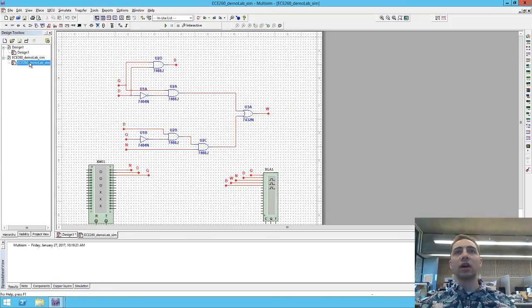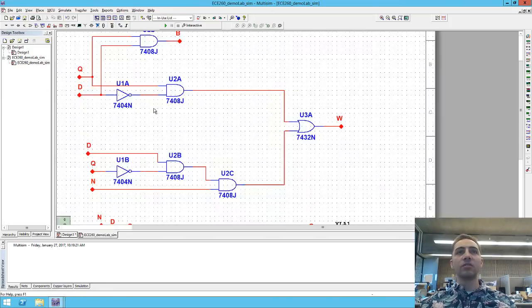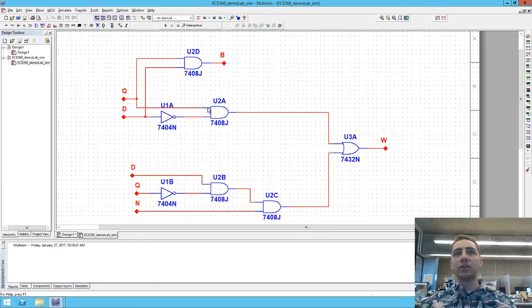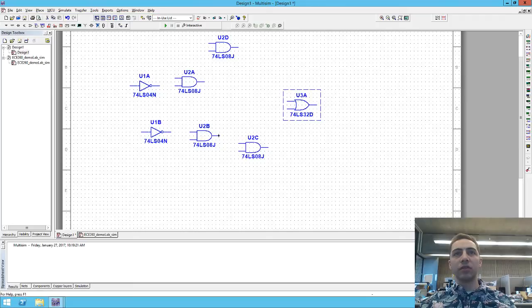If we look across, they're in about the same situation here. The 2 AND gates will connect to an OR gate. This AND gate will cascade. So let's just put those together. All I've done is I've clicked on the output pin of one of these gates, and unlike in Fritzing, it will auto-route the angles and decide where it wants to go. You can change it later by clicking on a wire and moving it around, but you don't have to. It will automatically do that.